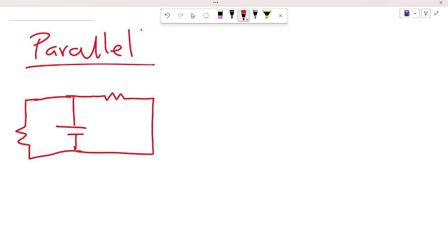That's a simple circuit, and we are going to use it to define how a parallel arrangement will look. The part I've indicated with the letter A represents a node, because as current flows and gets to point A, there's going to be a division of current as stated earlier. So that makes it a node.